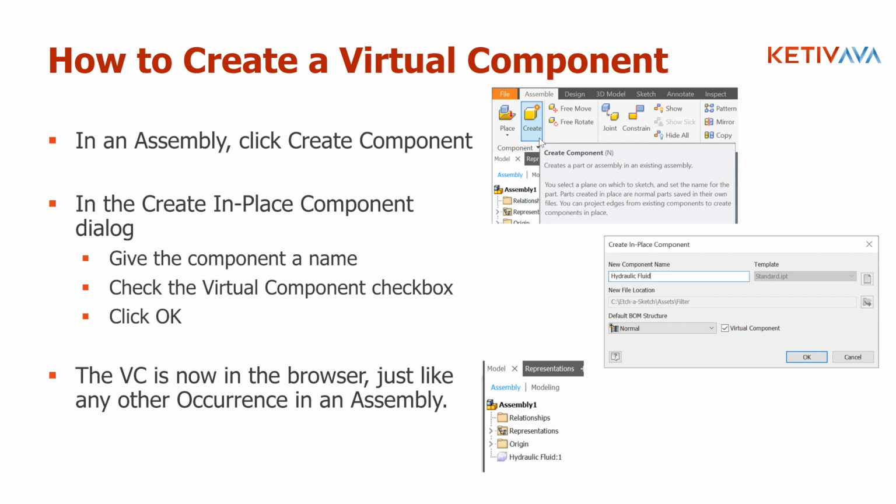I was going to ask if there's another way that you'd be able to find virtual components inside of Inventor versus just always through that create in place button. Is there a create virtual component outside of that? No, there isn't. That's one of the reasons why most people don't find them very easily, which is one of the reasons why we wanted to talk about them today, to make it more well known that they're there. Now, whether or not you use them or should use them, those are different questions, obviously. But you can't use a tool if you don't know it's there. So this is where you find it.